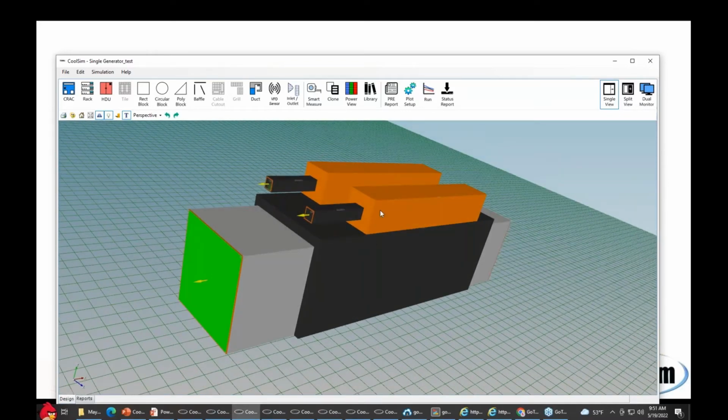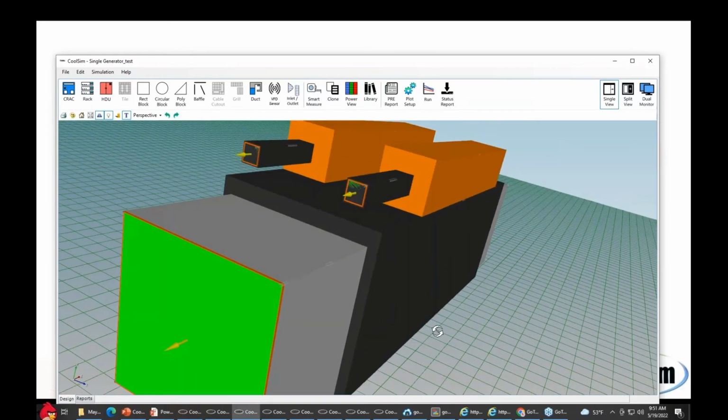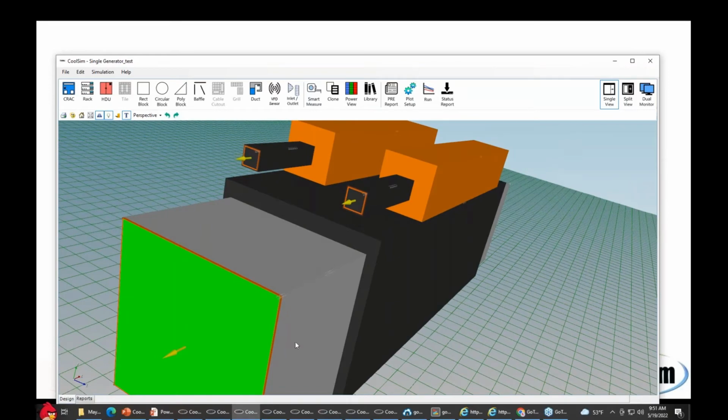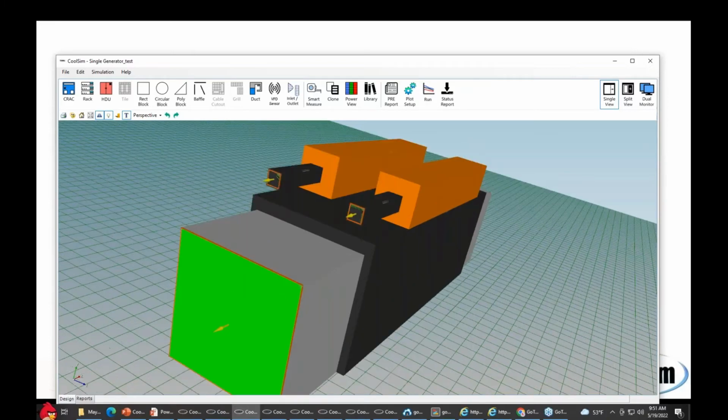So this is two banks. It's probably V12 kind of structure, and it's got two banks of cylinders and outlets. Now, what I've done here is just put inlets and outlets to represent those flow conditions. I don't really care about the delta T in it. I don't really care much about that structure, about that generator, except its heat coming out. I'm interested in particularly these exhausts and their flow magnitudes.